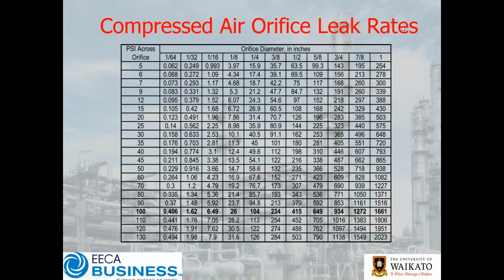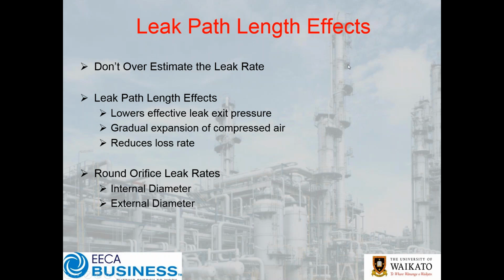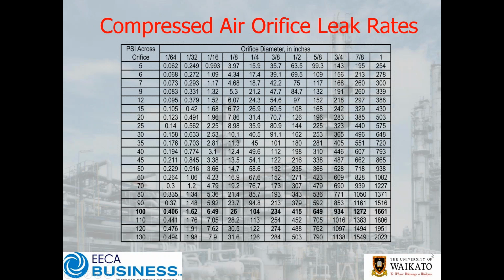in actual power usage. Now, the problem with this is the 1/4 inch figure is actually assuming a 1/4 inch hole, when a 1/4 inch tube is actually the OD, not the ID. So if we go back, instead of looking at the 1/4 inch number, we need to come down a size, and it's actually part way between these two, and you end up at about 50 CFM.